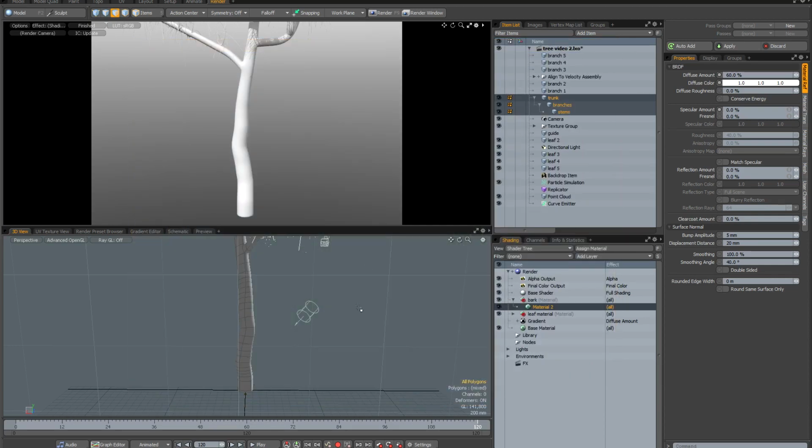And I think this is going to make for a very interesting texture. Now I'm going to create all of this procedurally because, well, two reasons. If I want to duplicate my trees, I don't want the texture to be duplicated. So if I have procedural textures, this is very easy to do. And the other thing is that when you've got something that's a complex organic shape like a tree, you don't really want to have to get involved with UV mapping it, not unless it's a very important asset. But if it's something that's just going to be in the background of a scene, you don't want to have to spend the time creating a UV map on an object like this. So procedural textures just make for a much better workflow.